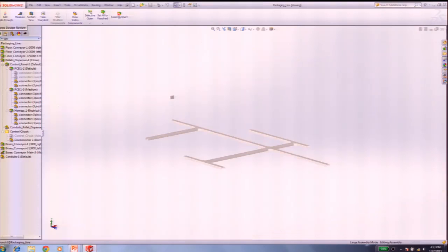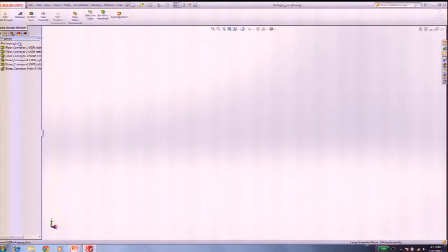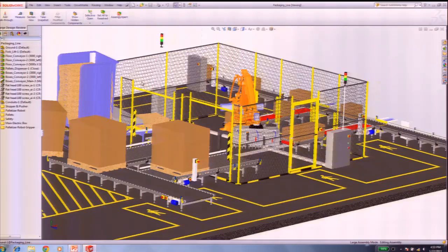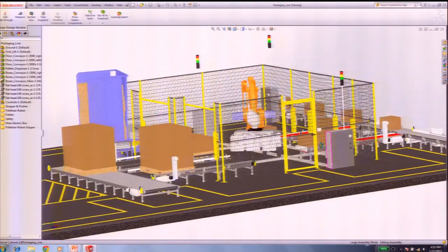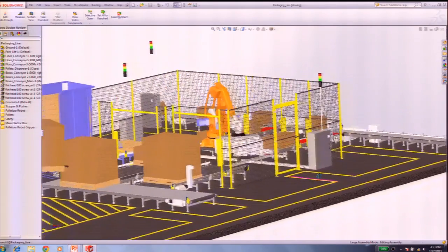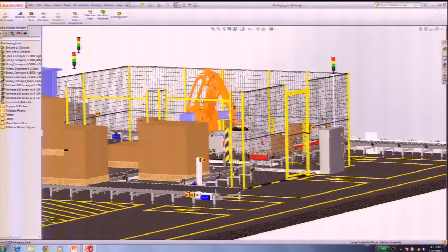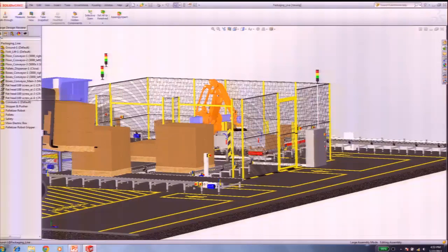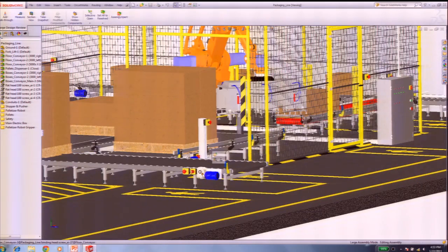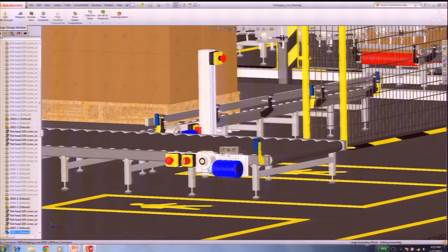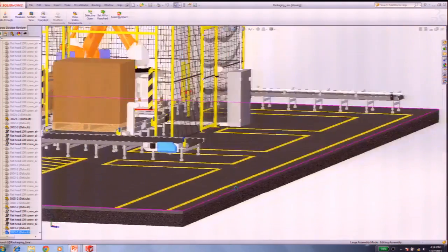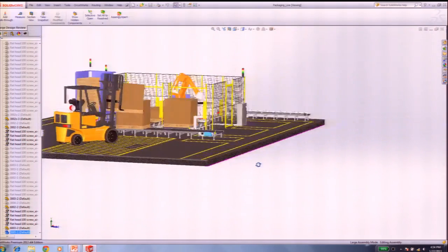Or we can look at conveyor. We've got conduit underneath to feed our electrical systems to our equipment. We can start to go in and look for other things. This is just basic SolidWorks sorting and filtering capabilities, and we can find our way through in this fashion. Then, using standard methods, we can say, hey, this motor looks interesting to me. I wonder who made this, or want to know something about it. When I click on it, it lights up in the feature manager. Or conversely, I can select in the feature manager and navigate straight to the item of interest. So that's all fundamental and works well as a way to get around.